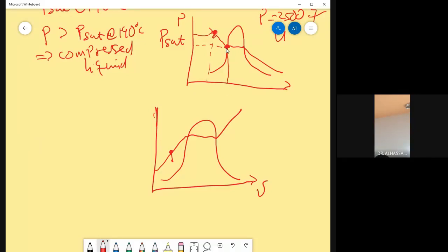So nobody will arrest you. Again, you find the UF over here, but at the given temperature, not pressure. At the given temperature means at 190 degrees Celsius, you are going to find this UF. You understand me? So UF at 190 degrees Celsius equals, again, the value that we have above. You understand me?